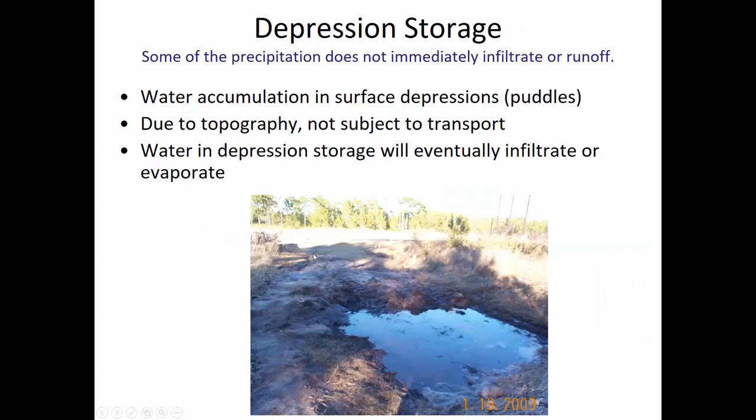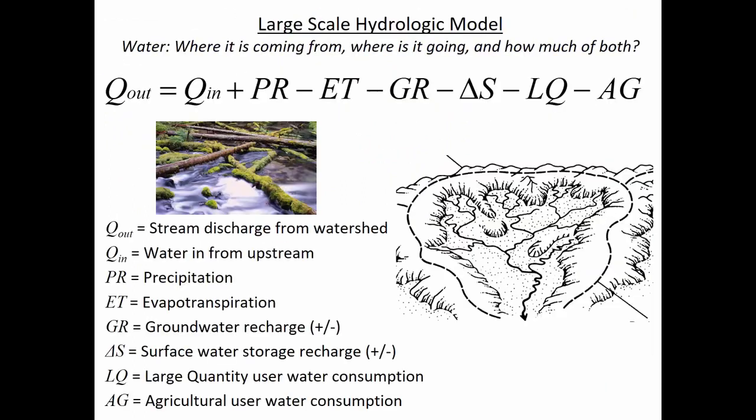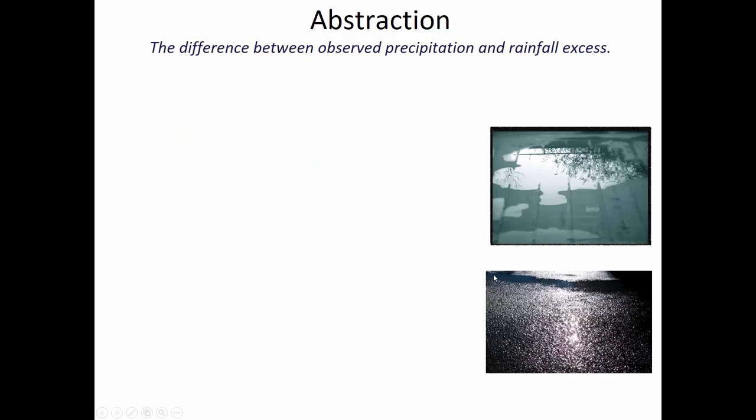Okay, so what are the other things that have to be satisfied before the runoff occurs? Well, one of them is depression storage has to be filled up. And in any kind of a regular watershed, there may be low points in the watershed that are not necessarily ponds, but they could just be places where puddles are going to accumulate. And all of that puddle area has to be filled up with water before there's going to be any lateral movement of the water through the watershed.